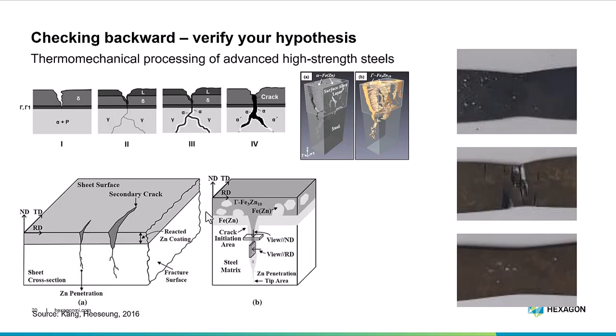And there's another problem that also happens sometimes in PHS. It's more common nowadays in resistance spot welding process, which is the liquid metal embrittlement. This is a problem that happens when you have zinc coating and a substrate that's very sensitive to grain boundary penetration by the zinc. To the right, what you're seeing here is a Gleeble test of a certain material where